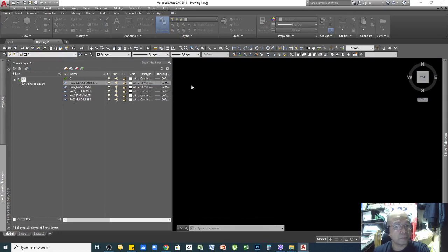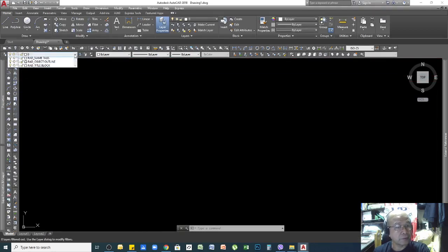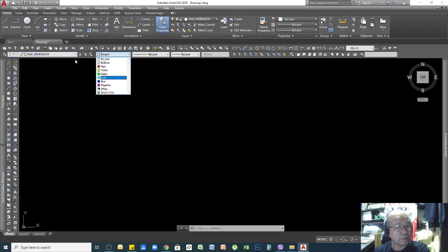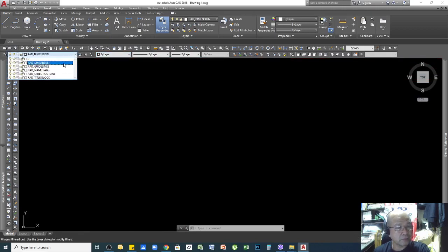It's not functioning here, so better you go here, click dimension, and then check, select for your dimension, just select by layer. That's it, because we need to set up later your dimension.